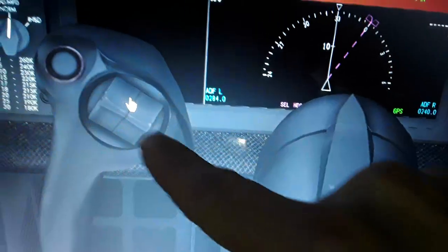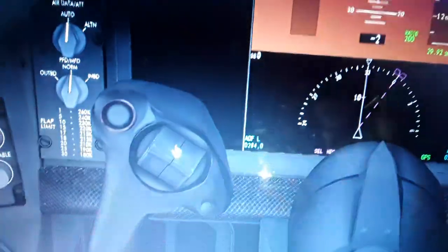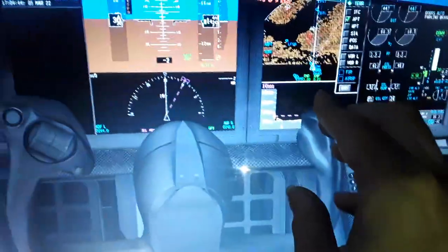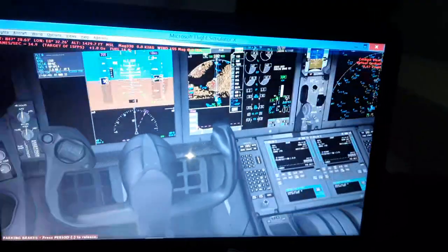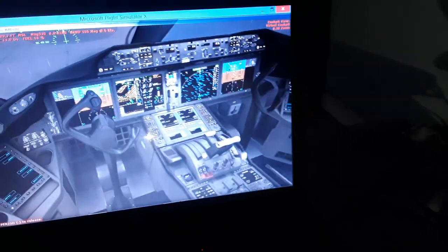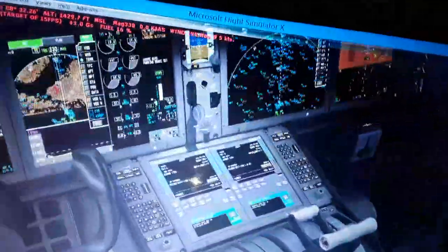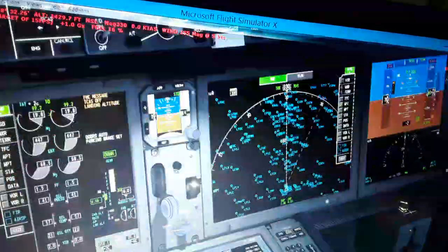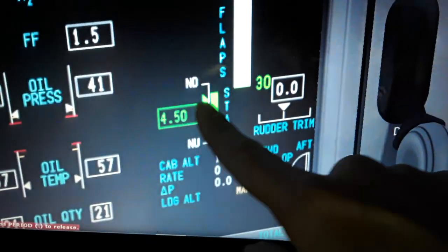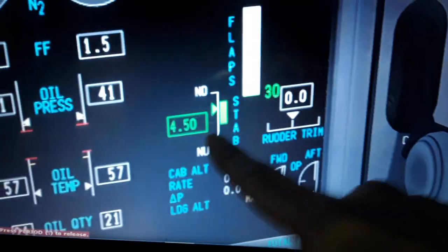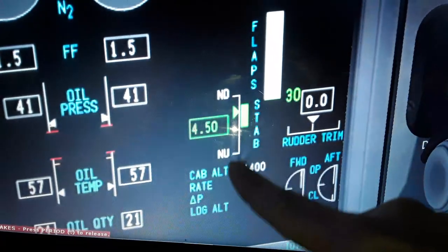We have the autopilot also disengaged, the head-up declarer, the flaps position over here. So this is the control wheel of the aircraft, as you can see. Also the control column for the elevator for climb, descent, make turns right and left. We can see also here the trim position. We have changed a little bit now. It's 4.5 degrees. You can see the green band is for takeoff limit, and also the white band is the maximum nose down and nose up limit.